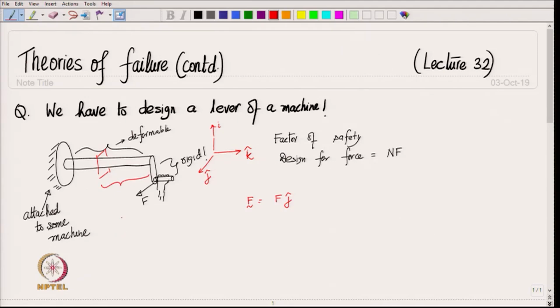So, here is the section of this shaft, and we are applying this force F here, and then at this end we will have negative of shear force V, correct, and negative of bending moment M, because that is the negative cross section, is it not.